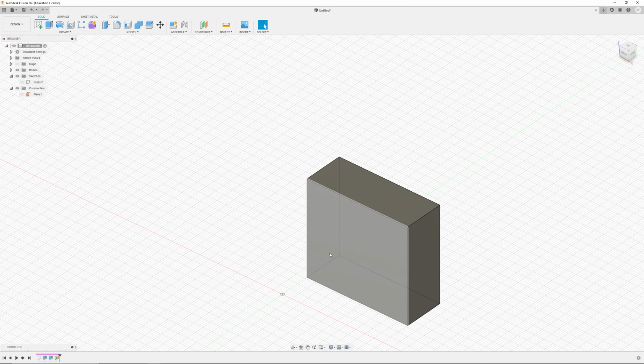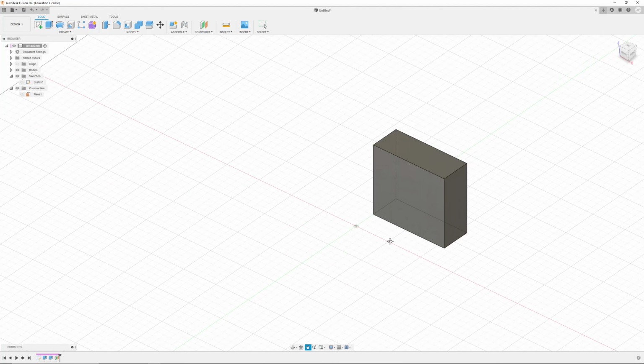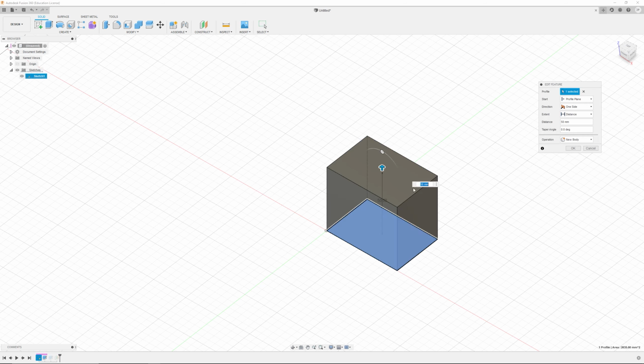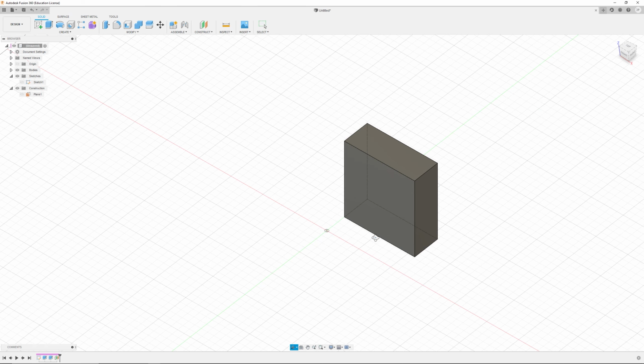One thing that I didn't say off the bat that I usually lead with is just that Fusion 360 is a parametric modeler. And if you are unfamiliar with what the terminology means, parametric just means that everything is assigned a value of some kind, and when I change that value, it will recalculate the shape based on those values. So for example, in this case, it's parametric because I can go back in, edit this, and make this a 60 instead of a 50, and everything updates.